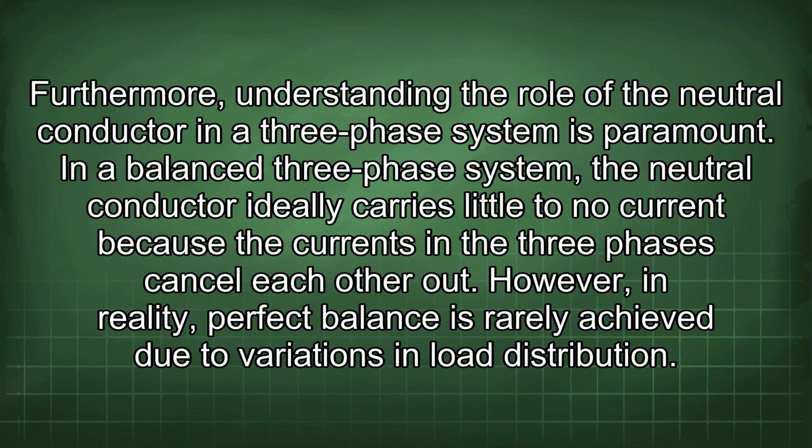Furthermore, understanding the role of the neutral conductor in a three-phase system is paramount. In a balanced three-phase system, the neutral conductor ideally carries little to no current because the currents in the three phases cancel each other out.